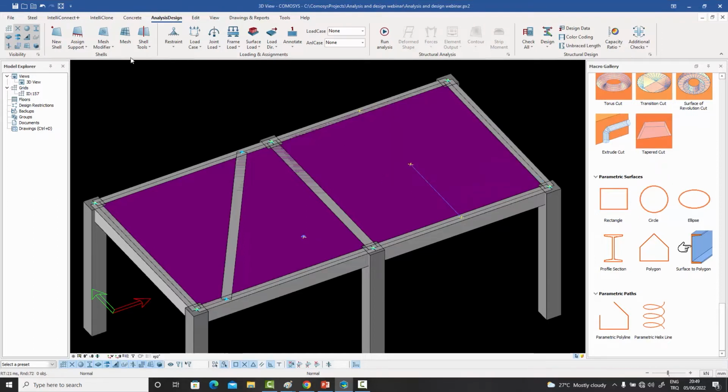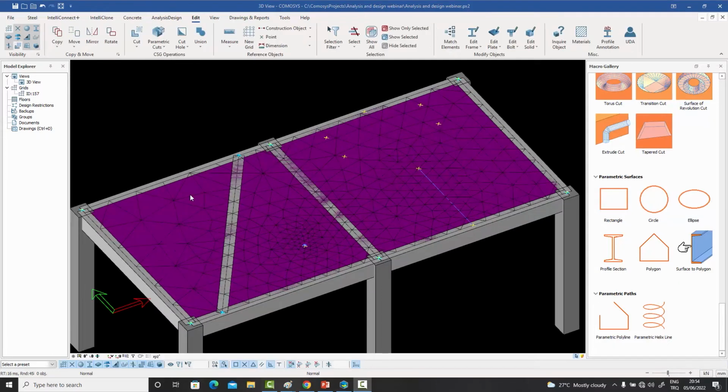And once we do that and we do the preview mesh again, we see that not only do we have this increasing mesh size around the point which meets up with this 1000 general density, but we also have the same phenomena going on around this line, and it's meeting up with the broader density of the slab as it goes out into the outer regions. But even that is not all.